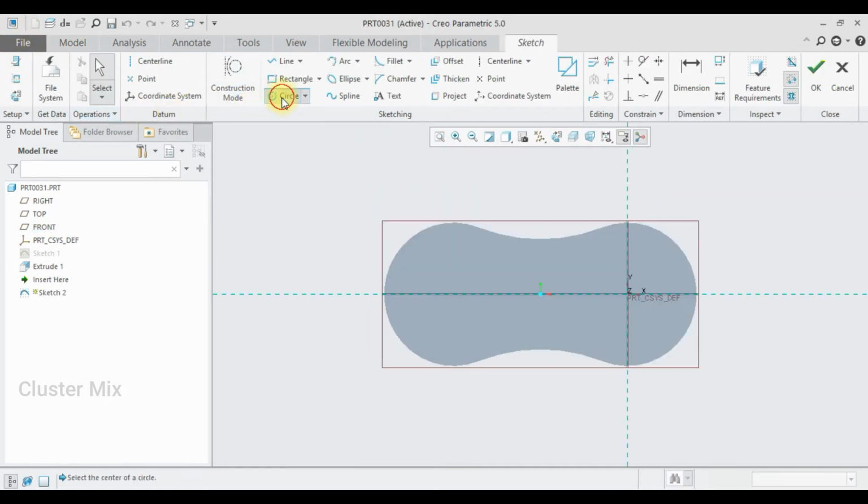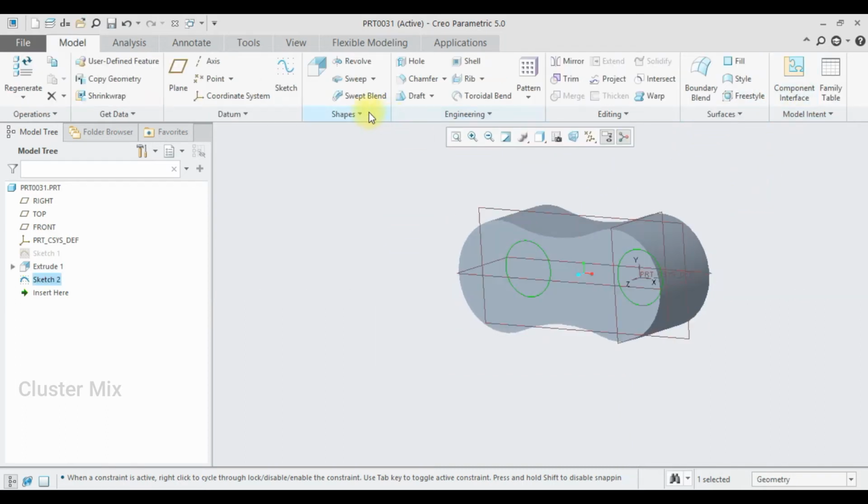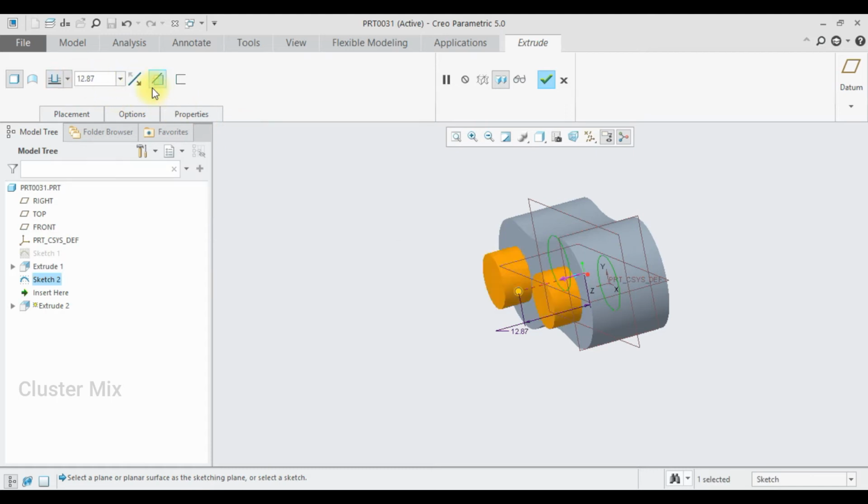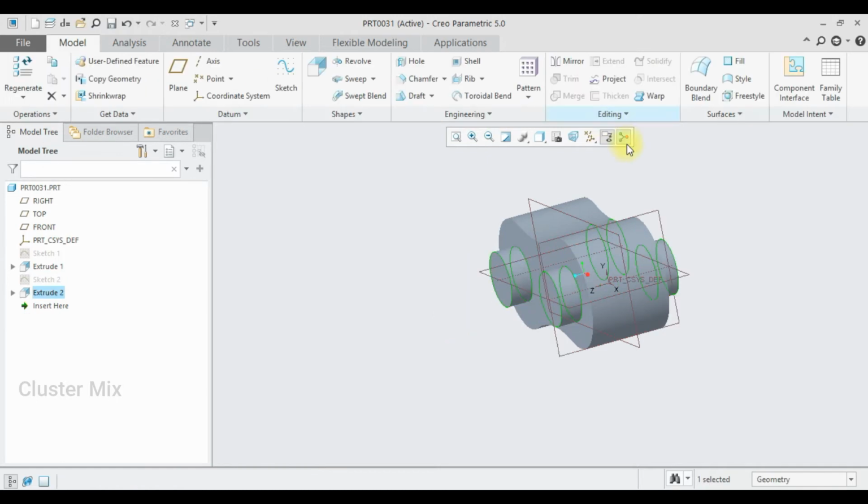And I'm going to select this place and click on sketch view, and here I'm going to draw the circle whose diameter is going to be 10, and then give a check mark to it. And now I'm going to use the extrude feature, and let me uncheck this remove material option, and I'm going to extrude it to a 23 by using the